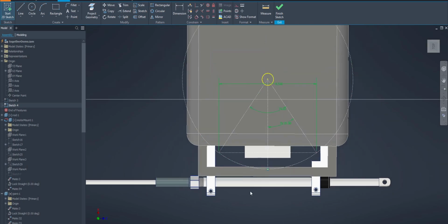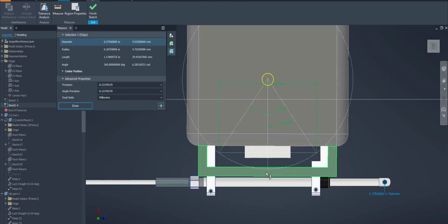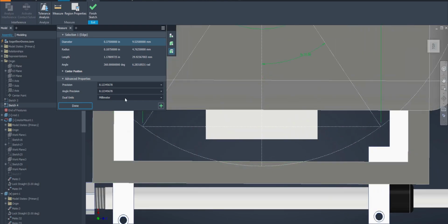Okay, and then the other thing I can do is, knowing that the motor is straight right now, it's going straight, if I make this rod out 4 1/4, which is half of the full 8.5 from limit to limit, then the distance from this hole to this point right here is the distance that this rod needs to have.